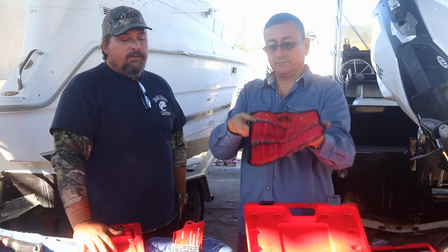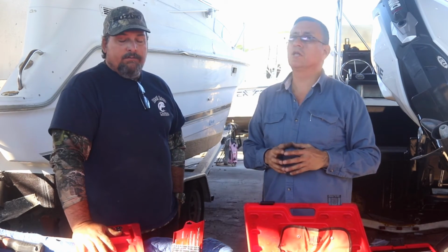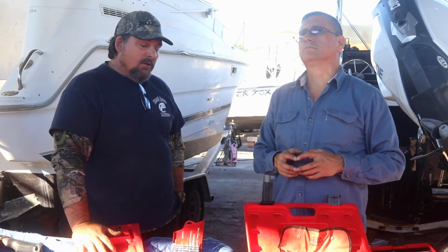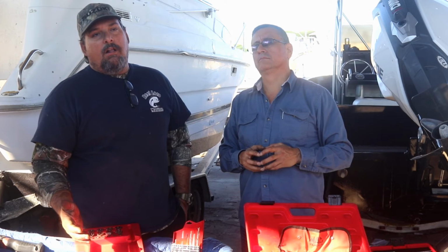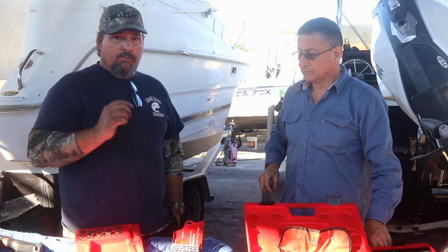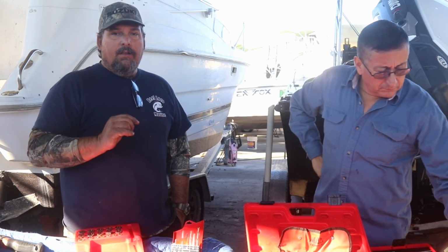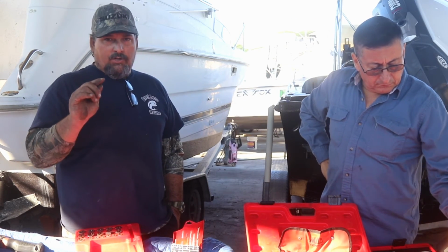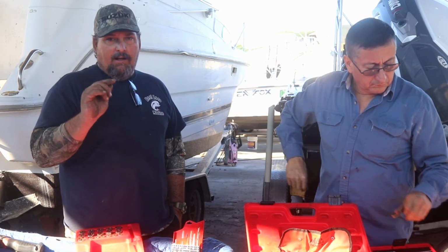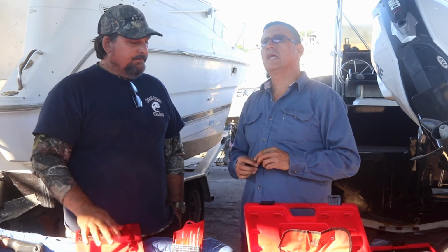You need the drill bits, the Home Depot drill bits? No, that's not good. You need to get carbide, titanium, the black and gold. They're like $200-300 for the drill set. But let me explain something to you. What happens when you use a cheap drill bit? You use a cheap drill bit and it breaks in the component, you're really in trouble, because there's nothing harder than a drill bit to get out. So it's important to use good quality drill bits.